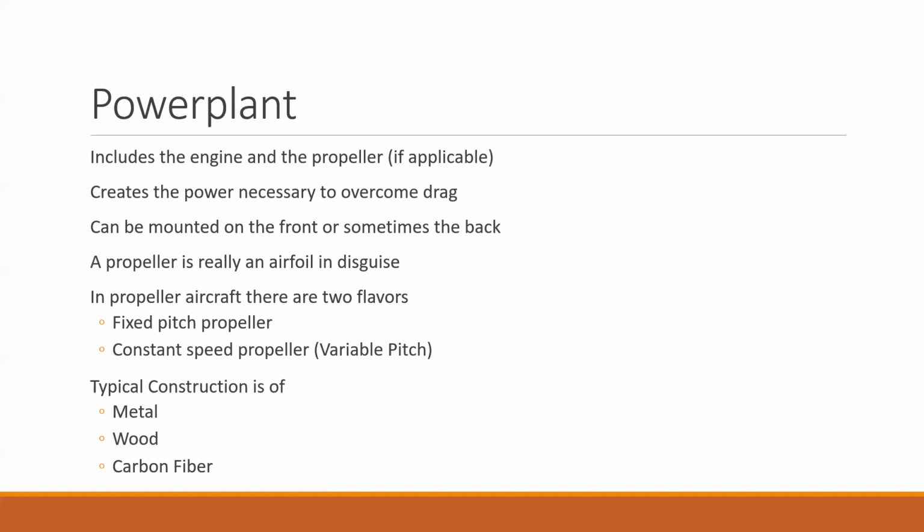As the engine runs up, it increases the oil pressure. This puts pressure on those springs, and it allows the propeller to go into a fully forward configuration, fully biting into the wind and resisting that force. So yeah, it operates on oil pressure and some springs. Pretty cool.